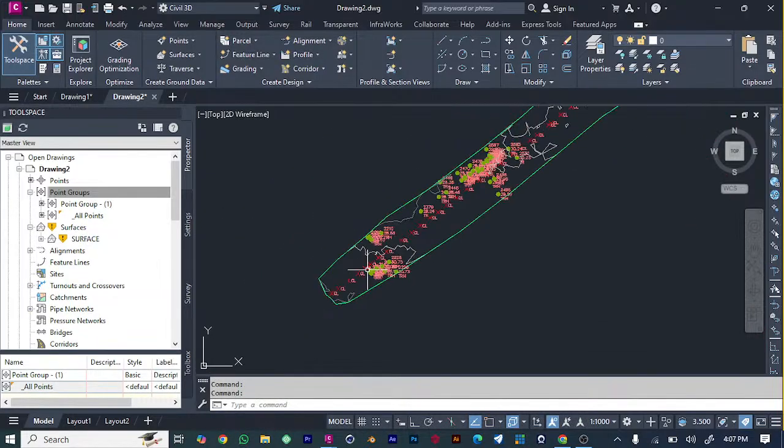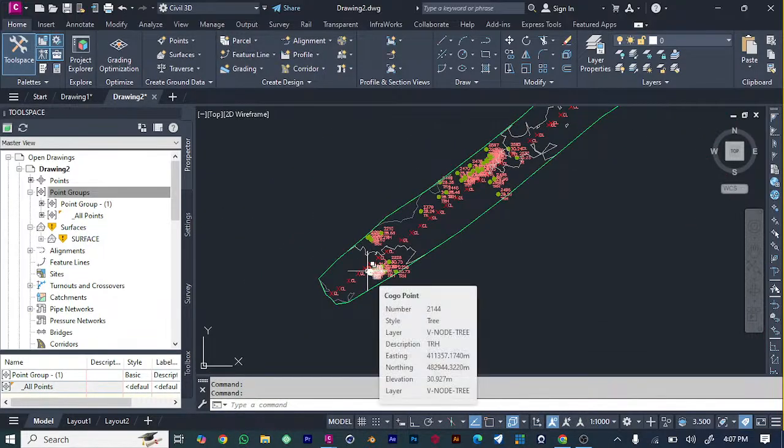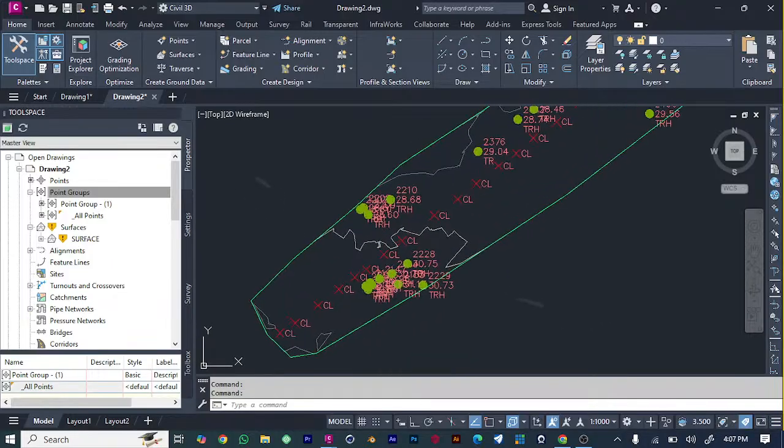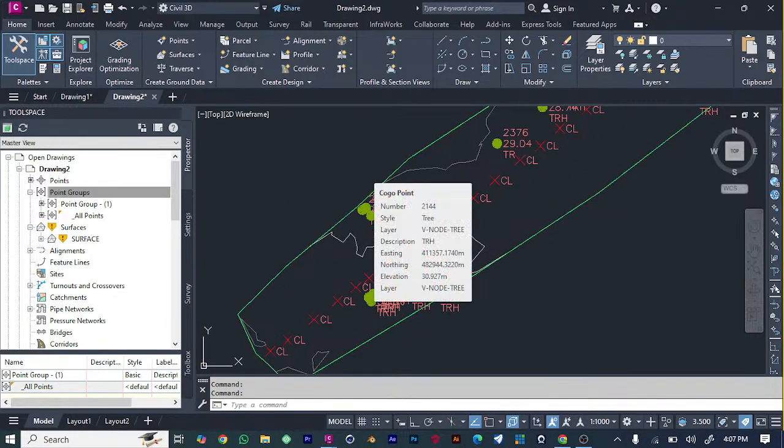So I see so many engineers doing it the wrong way. Like when you get a line, you just assume, let me hope that this is the center line. So ensure that the points you're given by the surveyor, you use them the right way to create your alignment. So this is how I do it. And then now I have my center line very well.